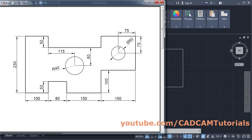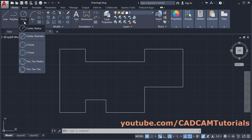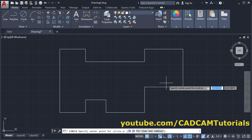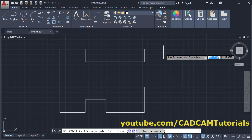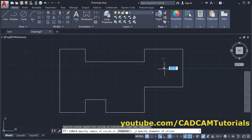Then next is this circle of 60 diameter. Now it is at the center of this square of 150 by 150 size. Click here and select center diameter. Then take your cursor to this midpoint. Don't click there. Then take your cursor to this midpoint. Again, don't click there and take your cursor in the center. So it will track those 2 points and it will locate the center of this square. Click there. Then give the diameter of 60, enter.